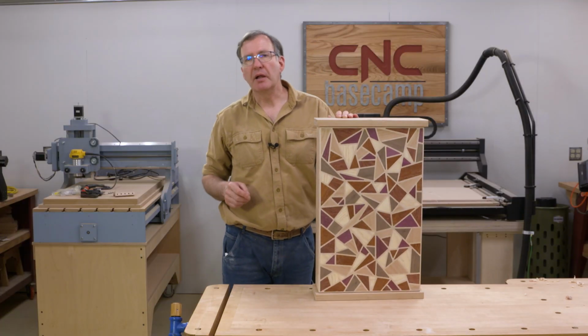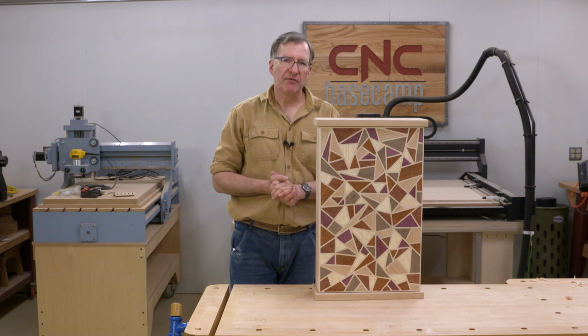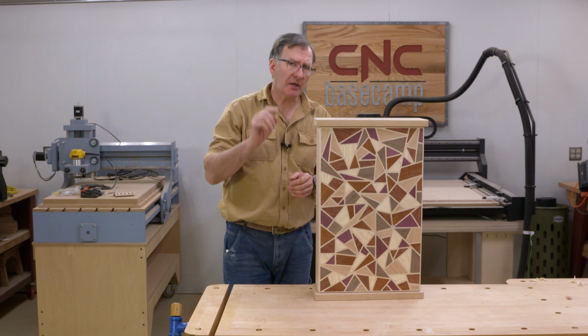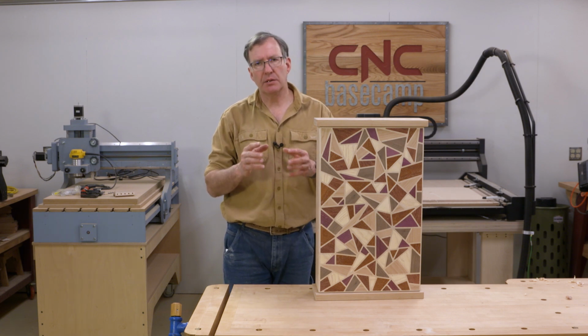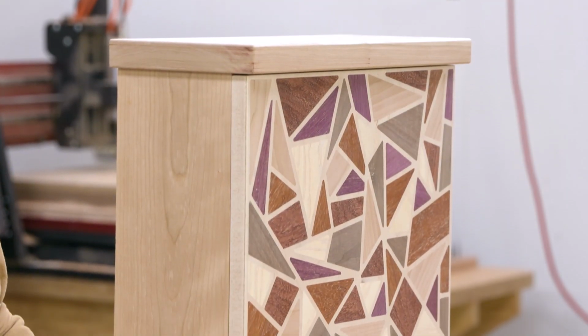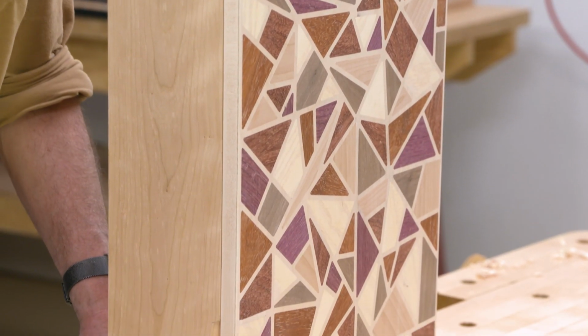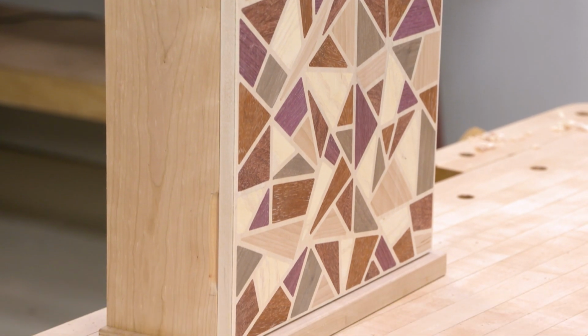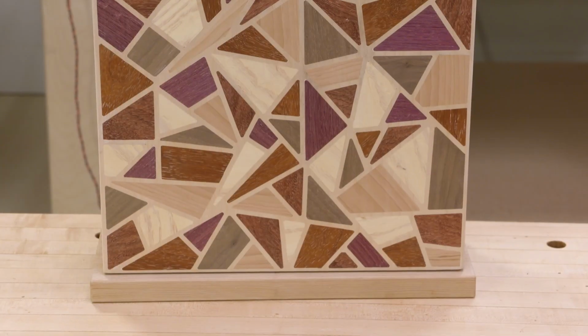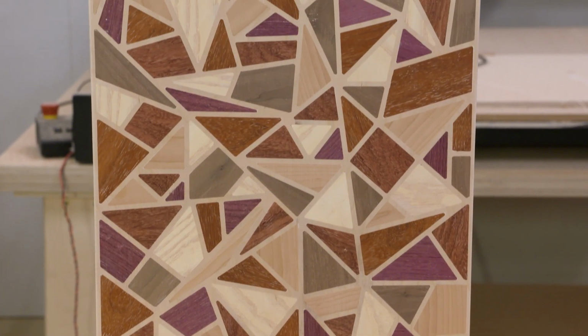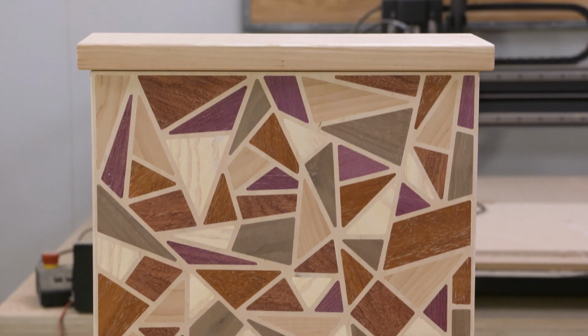To finish this cabinet, I'm going to use about 4 to 5 coats of a nitrocellulose lacquer, and I'm going to use lacquer because it doesn't impart color to the wood. An oil-based varnish is going to yellow things out a little bit, and I want to keep things very bright, very clean looking. An alternative to nitrocellulose lacquer would be any of the water-based finishes that are currently available. They really do a great job and they're very friendly for the home shop.